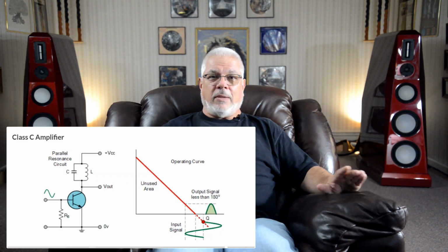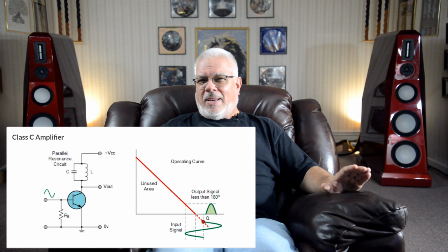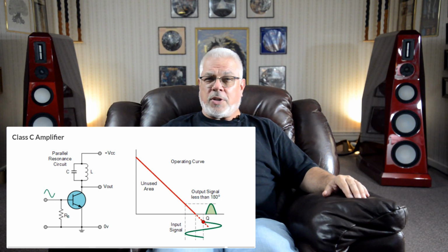And before we move on to another classification of amplifiers, there is also a Class C linear amplifier. And while Class C amplifier designs offer the highest efficiency among linear designs, they also offer the poorest linearity and are completely unsuitable for audio amplification. Now, next up are the newer switching amplifier classes. The most commonly used switching amplifier class used in audio applications is Class D.